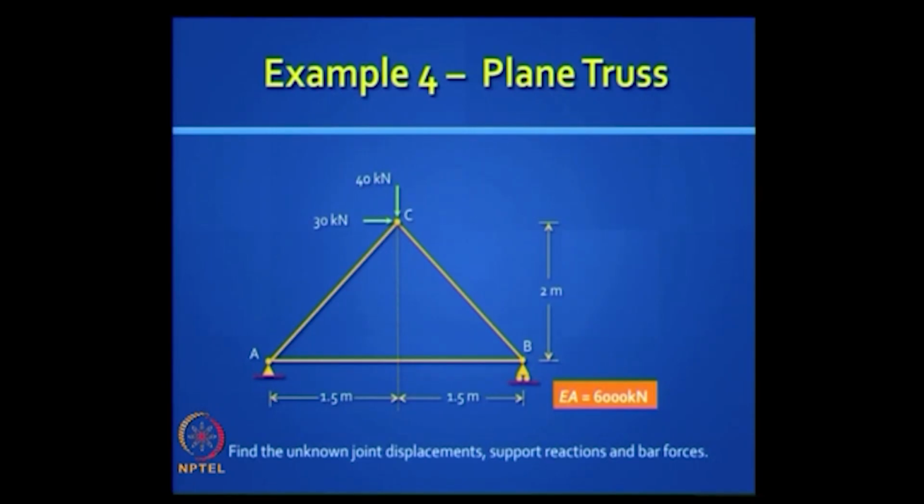But we don't want to do that method, we want to do it the hard way. We want to do the stiffness method, because did you know that the computer will only do by the stiffness method? Let us say you had a nice transmission line tower, spaced structure, it is mostly statically determinate, the indeterminacy is very low. So the standard software will choose to solve 120 equations simultaneously than do it by the force method, because you know that is how you program it, right. So this is a much smaller truss, very easy to do.